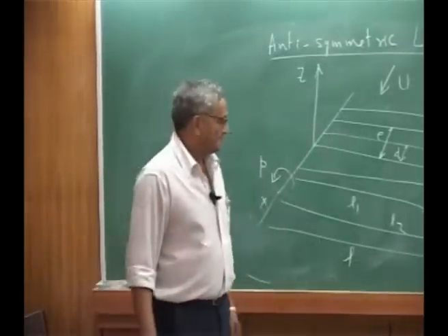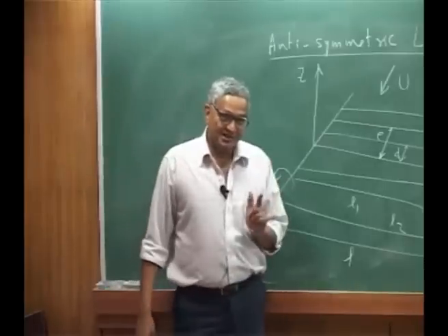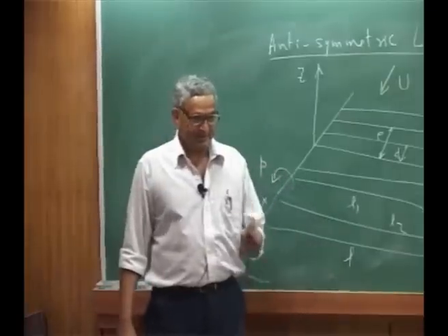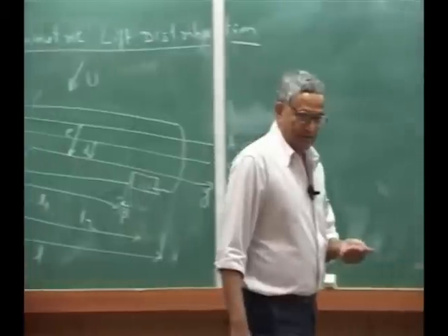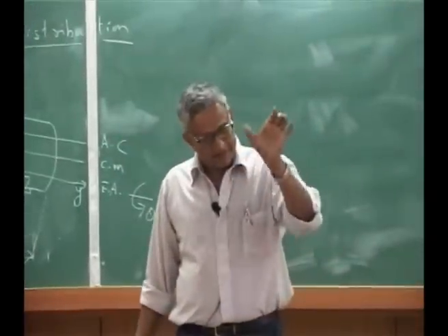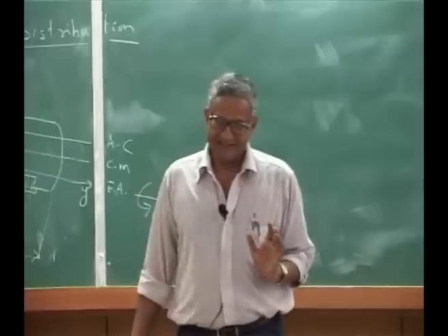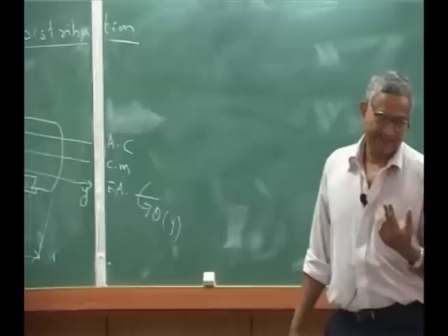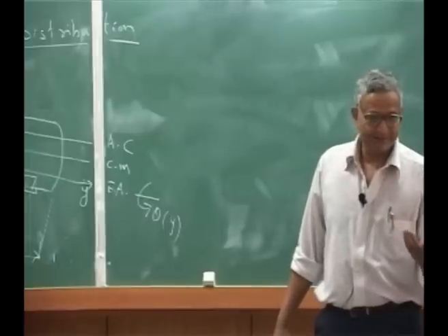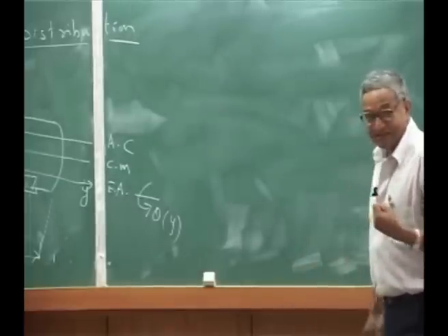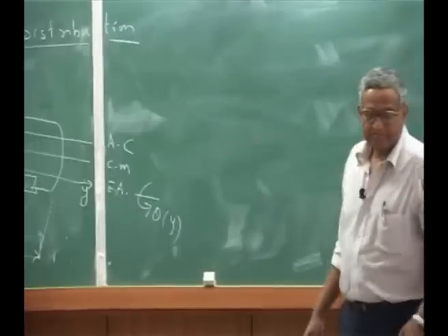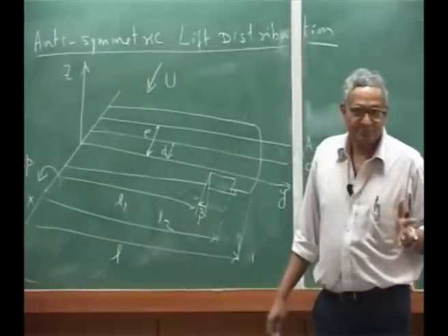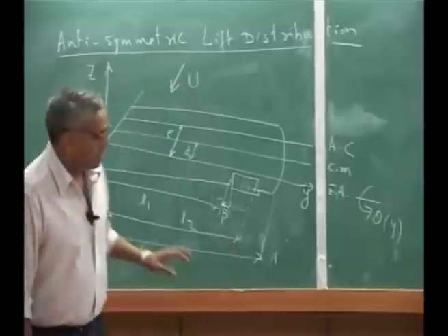The acceleration will go and change the load factor. Okay? Please understand, because the load factor, what is it? We took it as, actually, we say lift divided by weight. We take it as the load factor. But actually, these are all related to acceleration of the whatever mass of the element. Okay, that is why the load factor, when I start rotating, I am going to change my load factor on the wing. Okay. Now, how do I treat this problem?